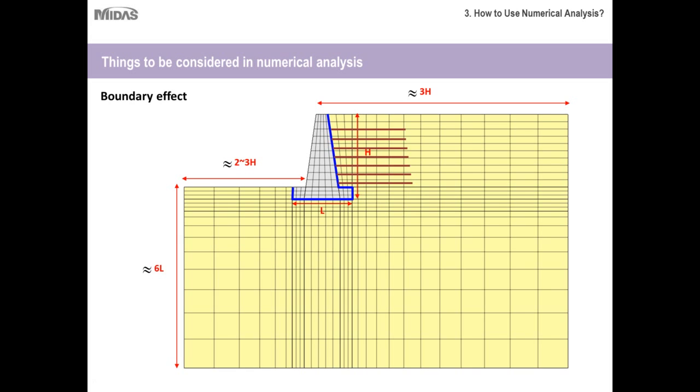Now, why were these empirical formulations or these boundaries defined? The reason for this definition is that whenever you are considering a finite element model, the stresses need to be dissipated in the neighboring soil strata. Now, to what extent would you like to see them dissipated? That is what determines these boundary effects. So let's say there is an adjacent structure here.